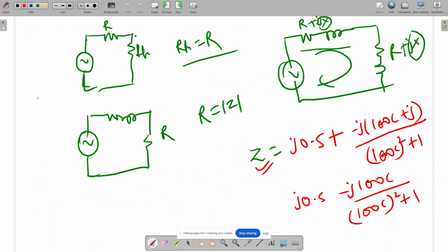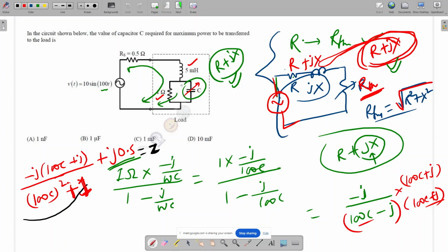For the maximum power transfer theorem, 2-3 varieties of question will be there. One will be this, one will be this, and if this will be there, then it will be Z conjugate. Okay, you can derive this. If we have a variable capacitance, then only when the reactive part is 0 is it drawing maximum power, that you can verify. For this also a derivation will be there in some book. Why, if the network is purely resistive, then only it draws maximum power. So that will be the condition. If the load is purely resistive, then it will draw the maximum power.